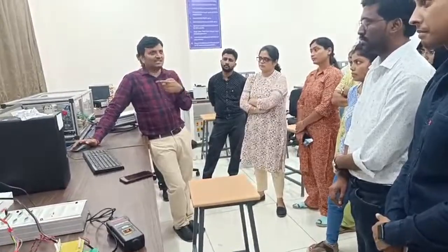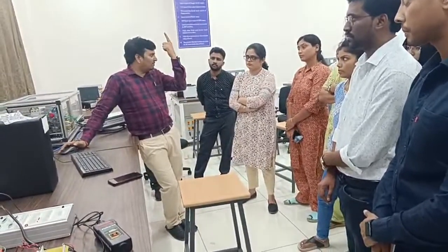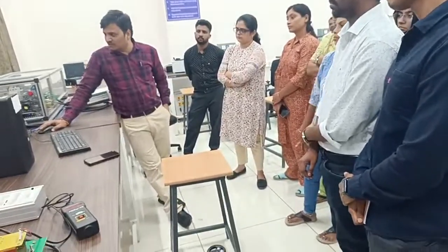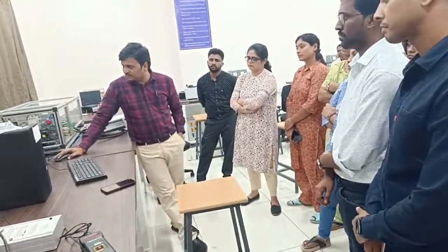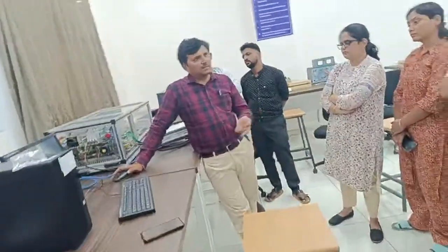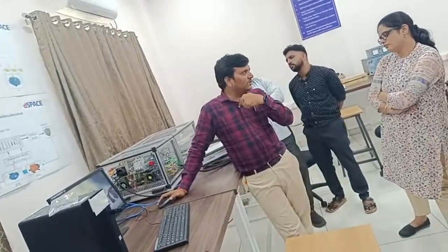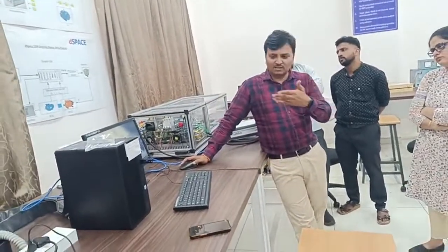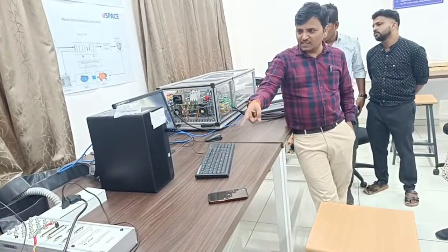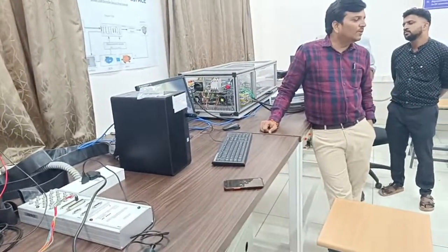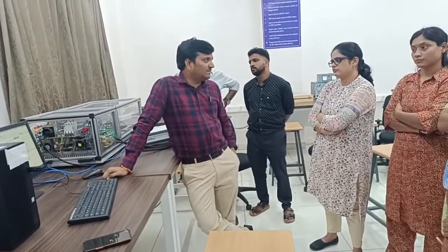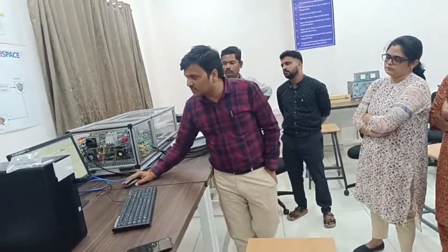Now to create the connection, I have to go to the ControlDesk platform. I have to open the ControlDesk environment. The platform is disconnected, so now I have to go to ControlDesk. I'll bring that pulse variable here and change the frequency so that we can observe what could be done. It is running now. During runtime, we can change the variable by using your SDF file.